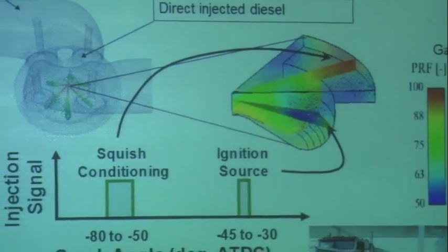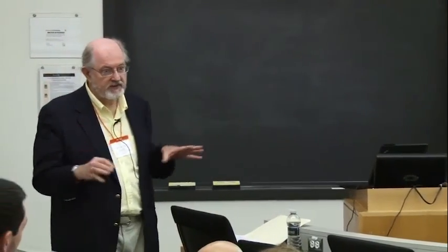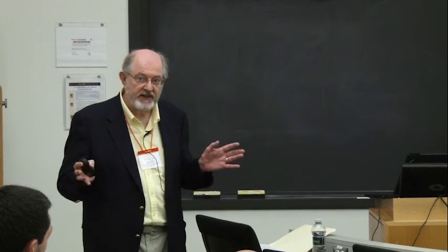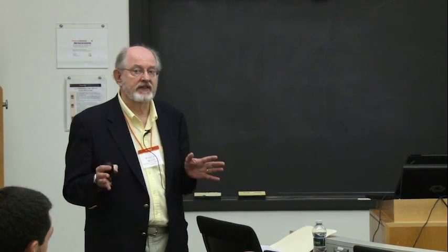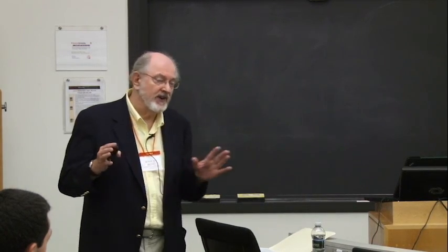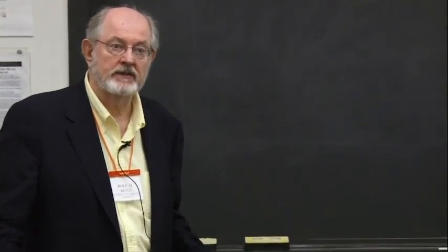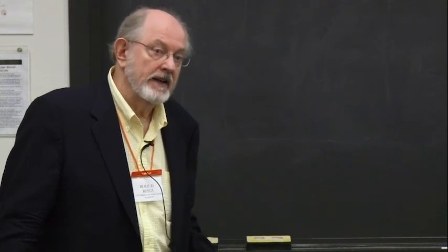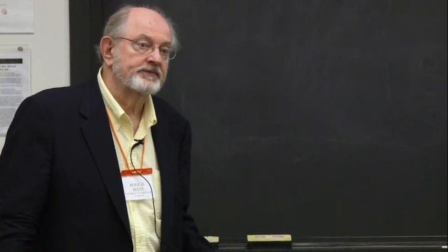This is with the well-stirred reactor. We've also done G equation modeling here, but generally the overall equivalence ratio is low, 0.3, 0.4. You wouldn't have flame propagation, or you wouldn't expect flame propagation to be important at low equivalence ratio. So you don't see any difference when you use the G model. Yep, we vary that as well.